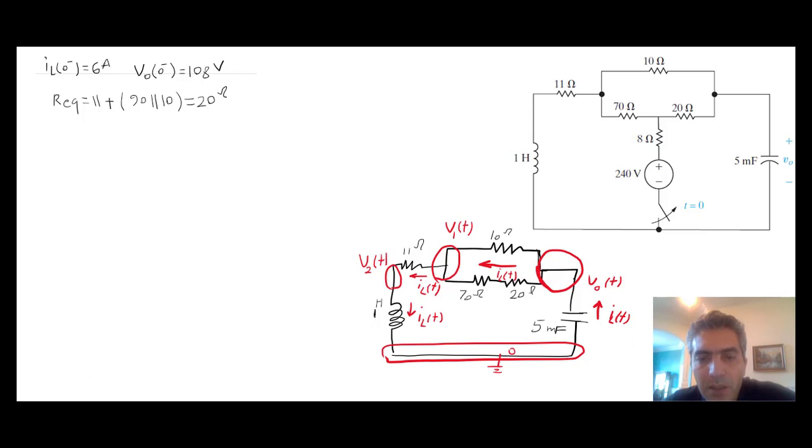So with that in mind, now just imagine that there's one capacitor, one resistor here. If you can't do that, just redraw the circuit. And there's no KCL to write. There's only one current in the circuit. So we're going to directly move on to equations for components. Now, for the resistor, this equivalent resistor, the current that is passing ILT is basically equal to V out T minus V2T divided by the value of the equivalent resistance, the 20 ohm.